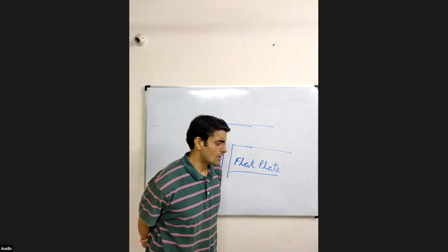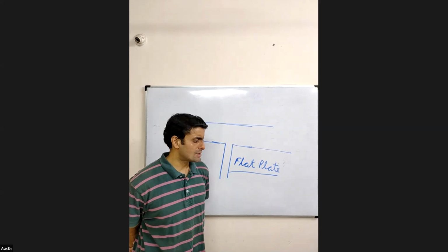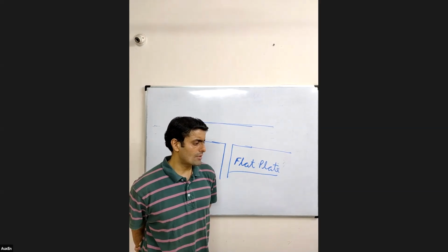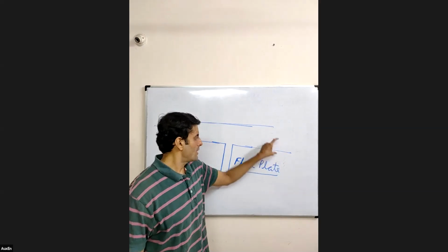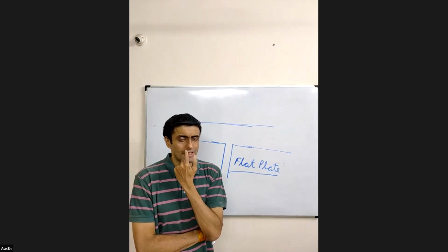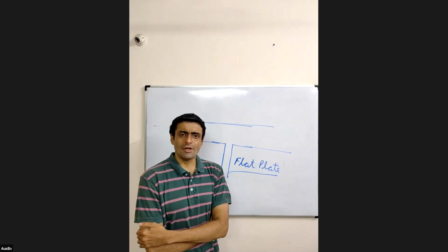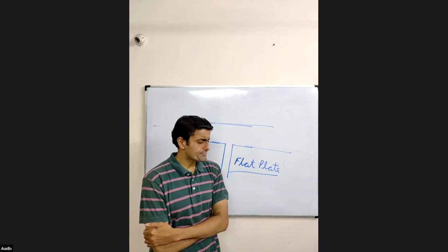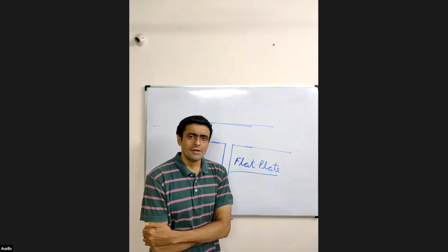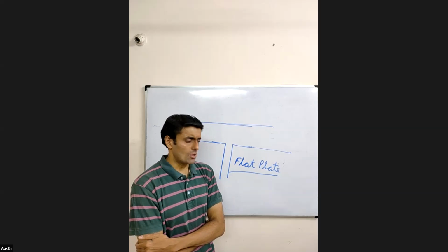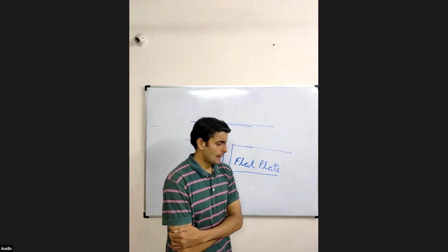So a general difference that you can say between a flat slab and a flat plate system is that in flat plate you have done away with the column capitals, drop, everything. You are providing a uniform thickness slab. So these we will call as a flat plate system. Otherwise, the working or the behavior remains similar for both, but just a change in name when we are not providing any column capital or slab drop. So we will call them flat plates. Are we okay with this?